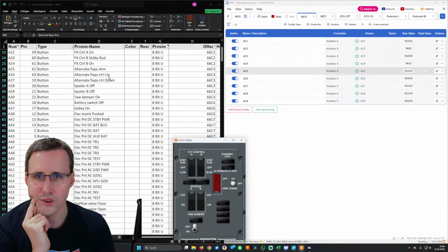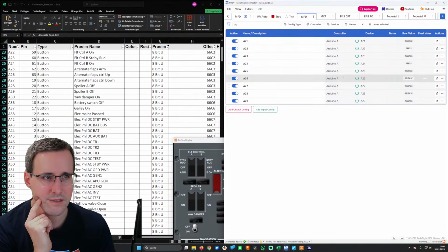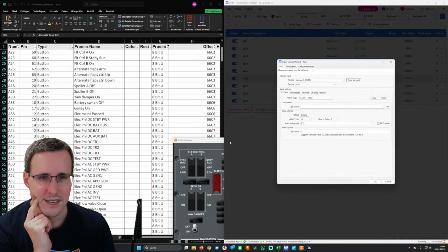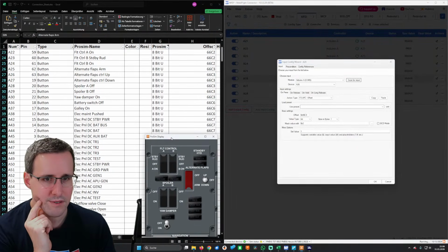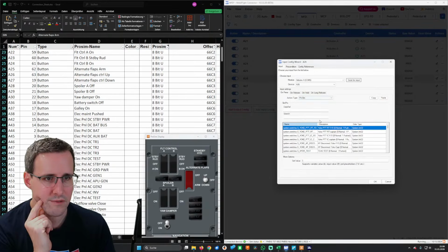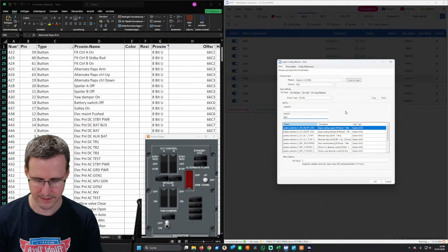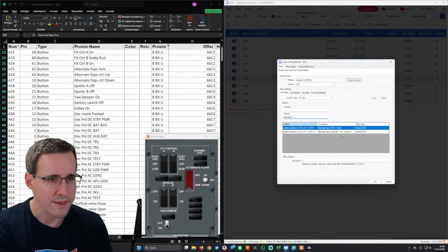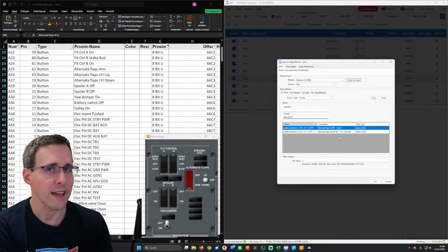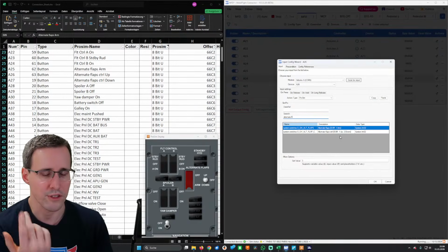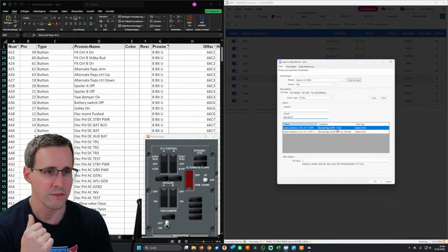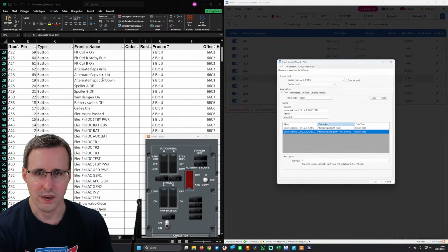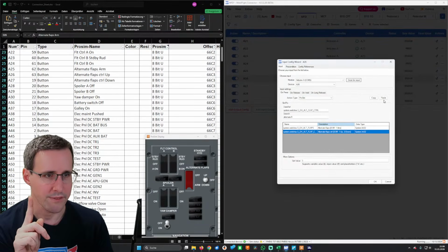Alternate flaps control up and down. This is, and let's bring this here a little bit over so you can see this. So this goes to Prosim. Alternate flaps here, and we have, again, like in the other switch before, a 3-position switch: up, middle, down. Middle, which is the off position, 0, up is a 1, down is a 2. So now we have up, this is the 1, there we have it.